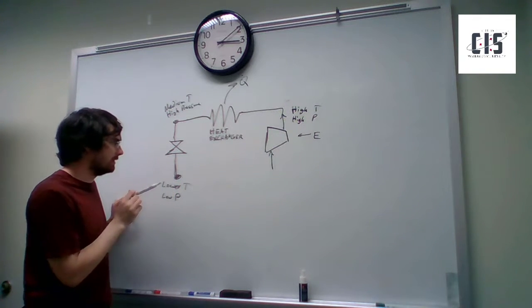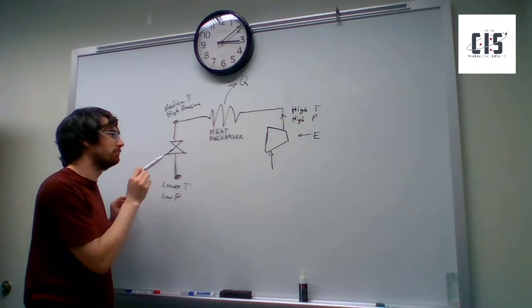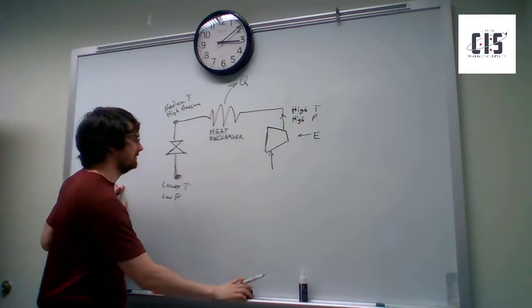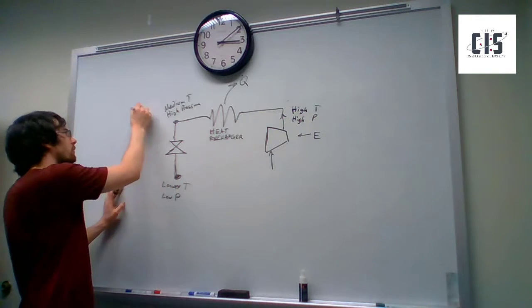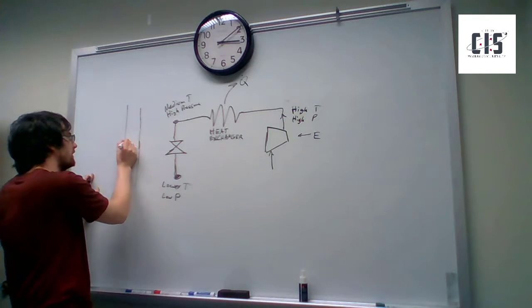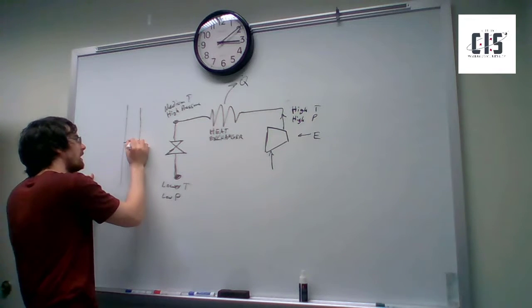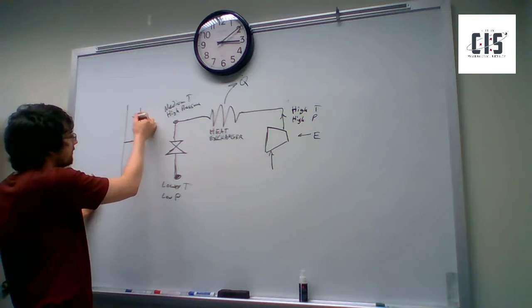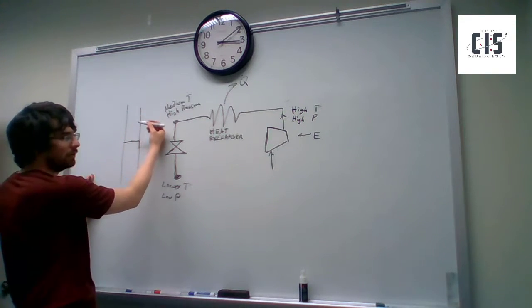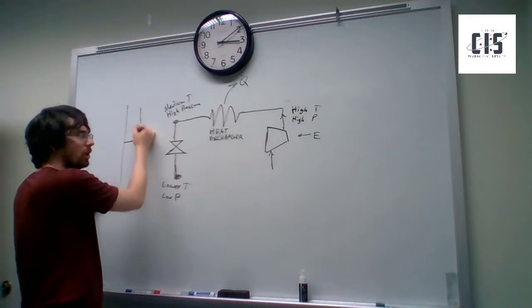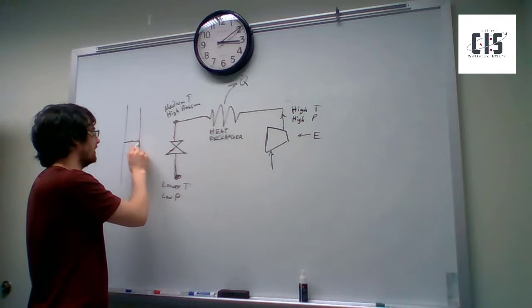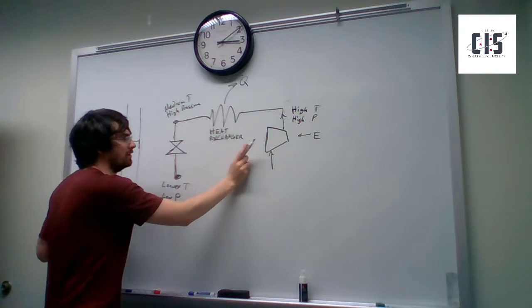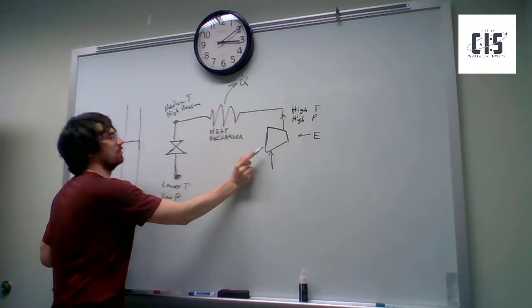There's actually a more efficient method. Yeah, so this is basically just an orifice. If you have a pipe going through and you have just a tiny little opening there, then assuming your flow rate is high enough, you get a massive drop in pressure across here, and then also a drop in temperature. But this is not as efficient as if we had expanded it in a turbine.